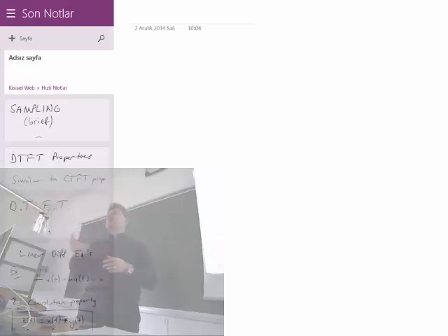The other one is the one that we have just seen in the last hour, which is the discrete time or computer processing of continuous time signals. And the way to do it is, again, as I repeat, sampling the system. You capture the low pass portion of your system, which is within the range of the bandwidth of your signal, and then repeat it. When you make a replication of those things, you get a sampled system. That sampled system corresponds to the system that must be implemented in the computer using your programs. And the output, you give it to a digital to analog converter, and the overall system acts like your original continuous time system.